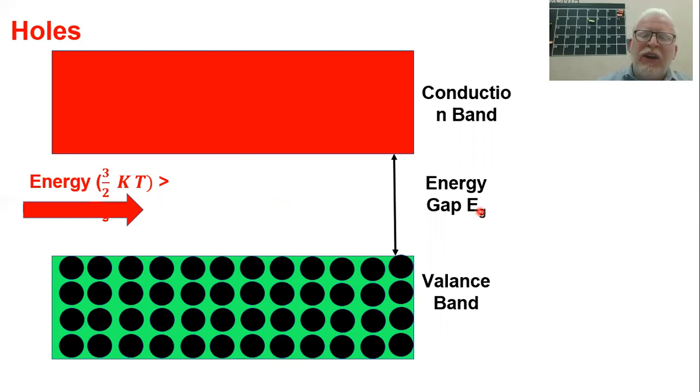Why am I mentioning this? Because if I asked you in this format, do we have holes in the conduction band? If you consider holes to be those empty spaces, your answer will typically be yes. We have a huge number of empty spaces in the conduction band. However, in the conduction band, you have zero holes because you don't have any broken bond.